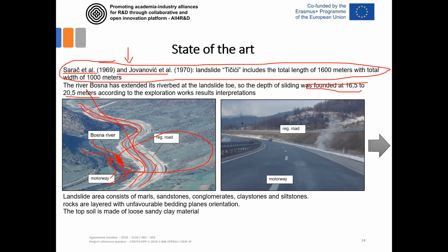If it is really a potential problem for this highway construction. At this moment, when these cracks were first recognized here and here, only remediation of the pavement surface was performed, by cutting it and replacing it with a new layer of pavement, and then it was flattened and continued to be used. But of course, some measures had to be introduced to keep this under control, and not have unexpected problems like a sudden increase in displacement that could stop this highway route.